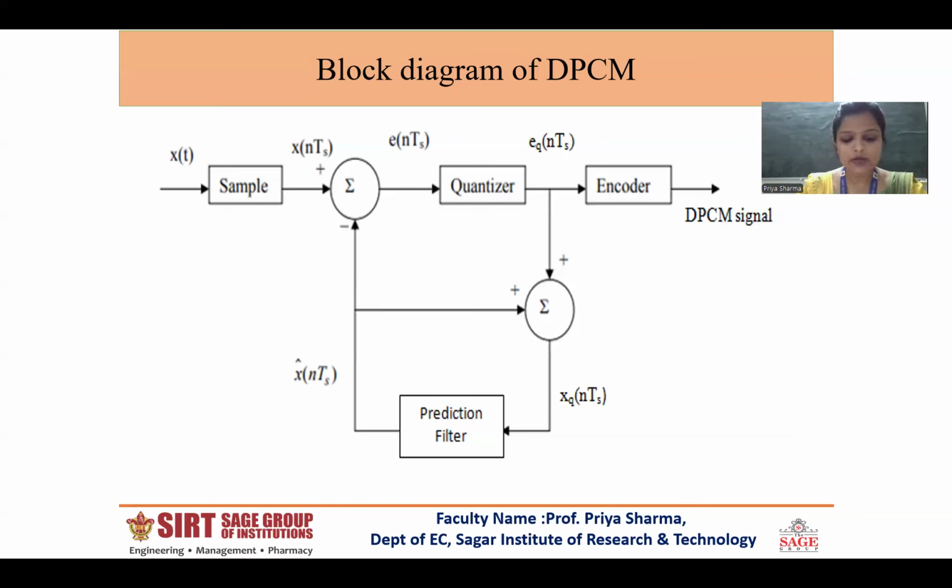The resultant analog difference signal is held constant by the sample and hold circuit for the duration of the interval between sampling times. The quantized differences are converted into a serial binary bit stream before transmission as DPCM signals. Thus, the analog difference signal is PCM encoded and transmitted in the same way as a conventional PCM system, except the analog to digital converter uses fewer bits per sample.